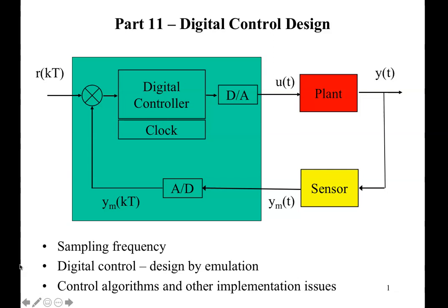If you have a discrete time transfer function and you find the poles, you don't want the poles to be negative, you want the poles to have a magnitude that's less than 1. Okay, sometimes I get muddled up myself. For continuous time, you want the poles to be negative. For discrete time, you want the poles to have a magnitude less than 1 for the system to be stable.